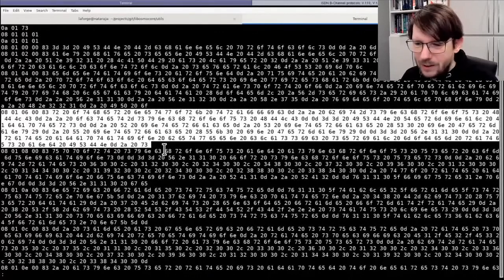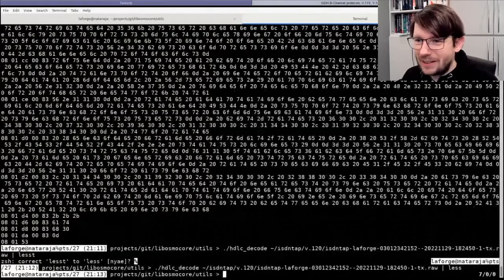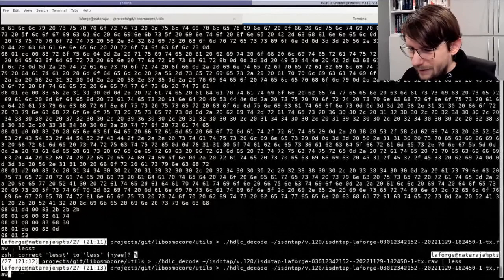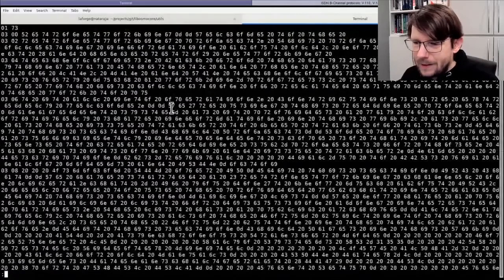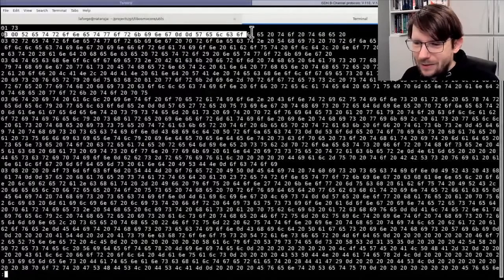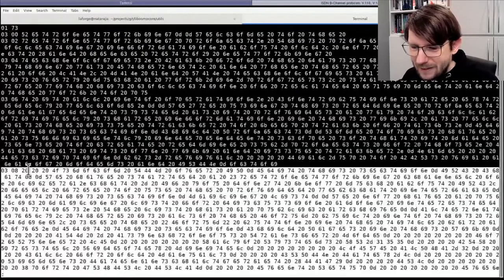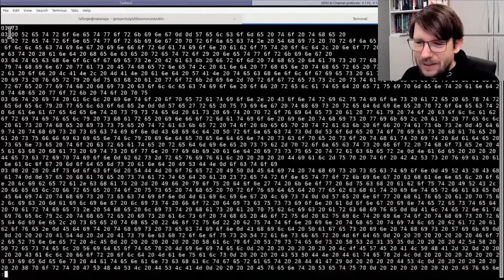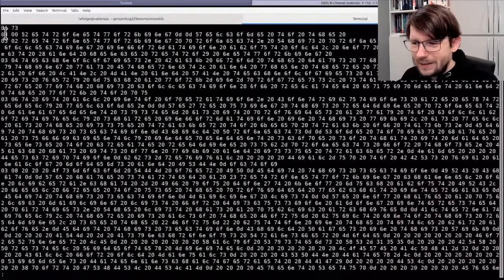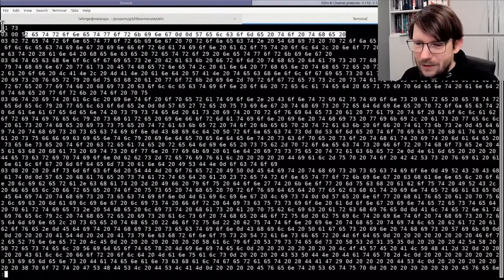That's also, I think, a very good way to identify which of the B-channel protocols it is if you wanted to do a brute force detection or something like that. And if we compare that with an X.75 trace, it looks like this. And here we see it's 03 and 01, the address octet, always the first octet of each frame. As you remember, those were the addresses A and B in the X.75 specification. And here we have basically address, control, and then the information part of the frame. And here we only have address and control.